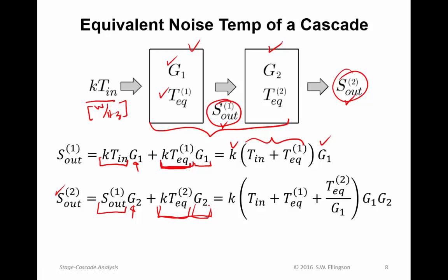So now making the appropriate substitutions and factoring away here, I get a K out front, I get the cascade gain, G1 times G2, and inside here I get Tn plus the input referred equivalent noise temperature of the first two-port, and then the input referred equivalent noise temperature of the second two-port, but now divided by the gain of that first stage. Now take a look here. In this first expression, this quantity here maps to this whole quantity here in the second expression.